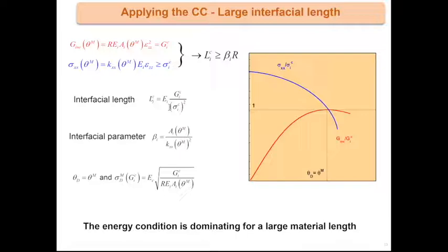Okay, and if this condition is satisfied, that is to say, if the interfacial length is large enough, then the energy condition is satisfied independently of the stress condition. So in this case, the controlling mode is the energy condition.